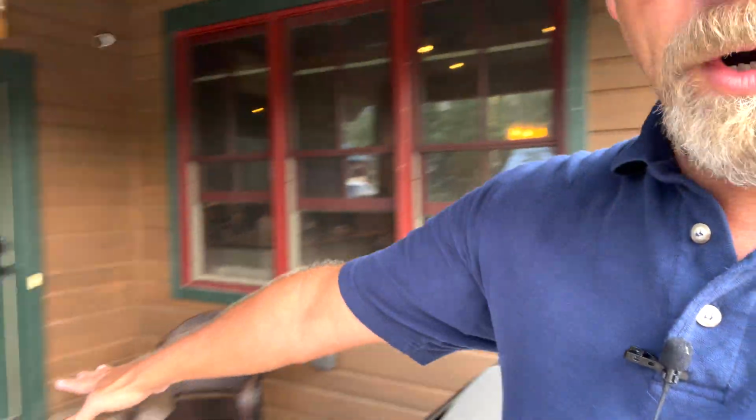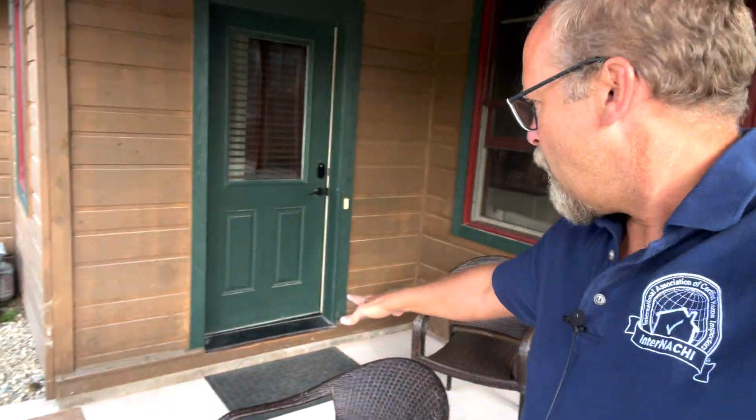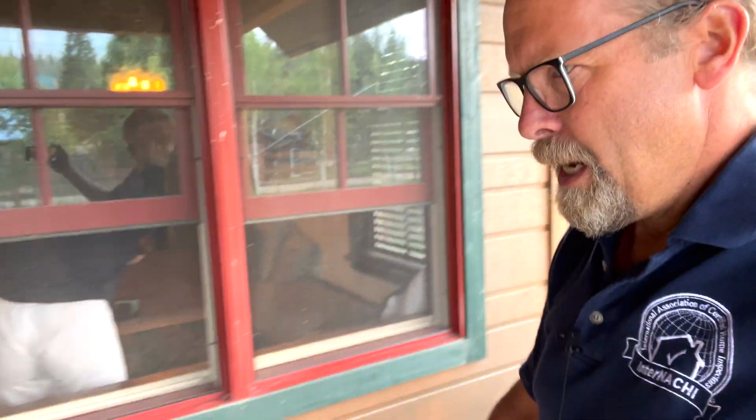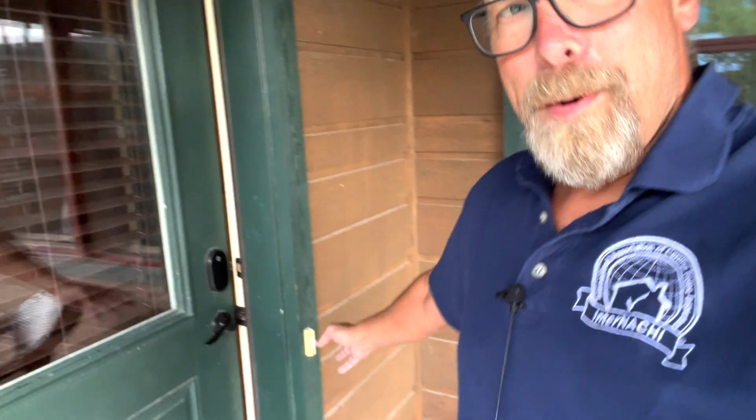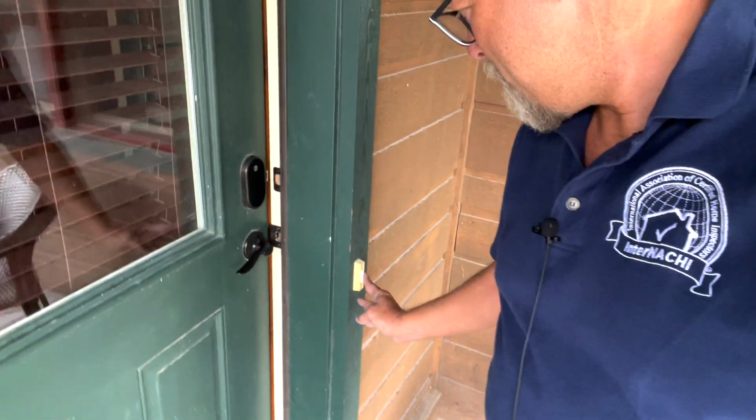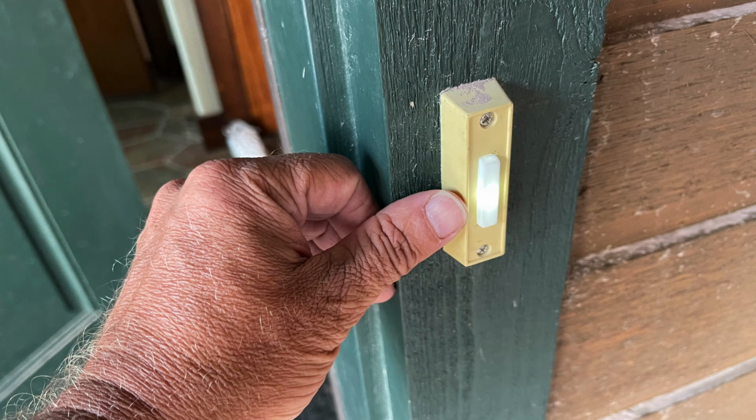And there's the front door area. I'll take a look at all exterior doors. You're required to inspect all exterior doors and a representative number of windows. And I'll test the GFCI. This is a cosmetic item, but always ring the doorbell for my client.